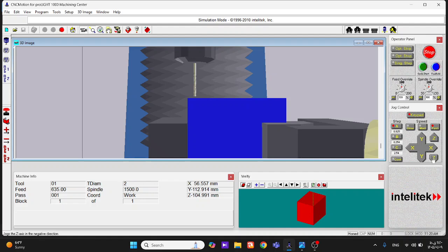In a real scenario, I told you, you cannot just come and touch the specimen because the specimen will be damaged or scratched. So how they do it in the real workshops, they assign this distance between the end of the tool and the surface of the specimen. They make it the height of the paper, and the height of the paper is 0.002.